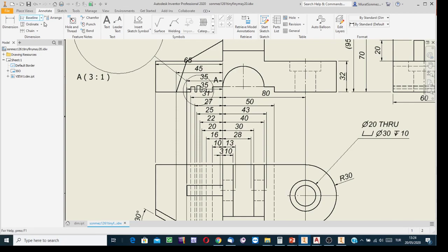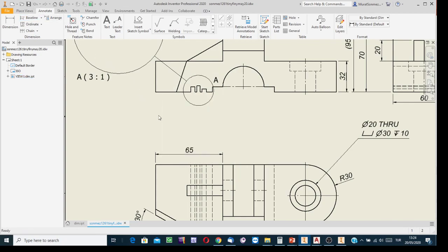It is wrong. Although it is a facility, it is not recommended to use, because Inventor cannot distinguish whether that dimension is to be shown. But of course, you can do this. After starting the baseline process, indicate the features, not using the windowing method for all, but some of them. For instance, I indicated this one, that one, this one, and this. Right click the mouse and then continue. Then only for the indicated ones, Inventor shows the dimension.